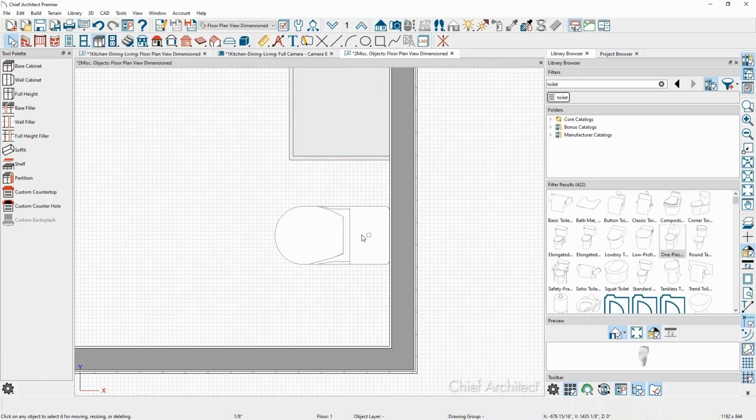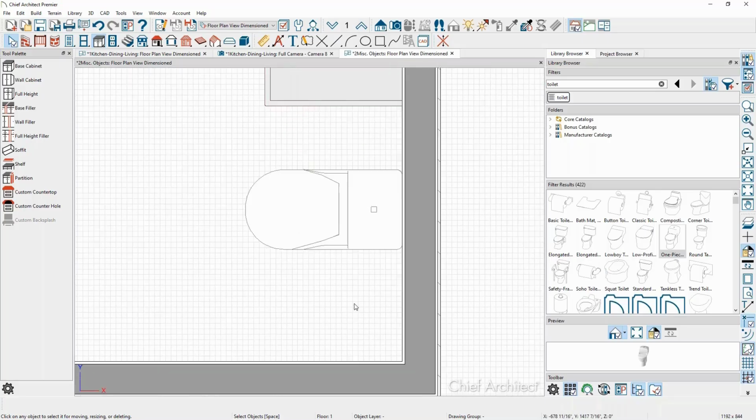Got it. So you want to make sure that from the toilet to the cabinet there's 12 inches, and from the toilet to the base molding there's 12 inches as well. Right, and then the third scenario is from that cabinet over to the wall. What's that dimension from the end of the cabinet to the baseboard on the wall? The baseboard obviously takes up a little bit of space from a vacuuming perspective. Got it. Okay.